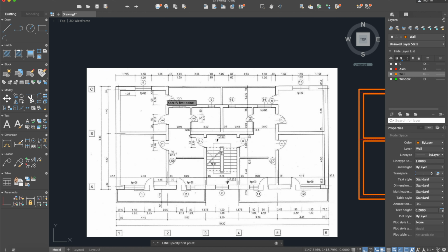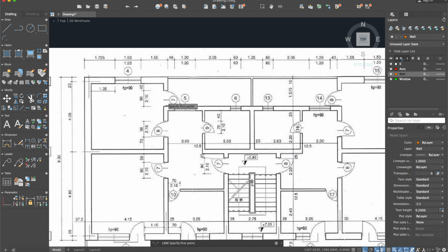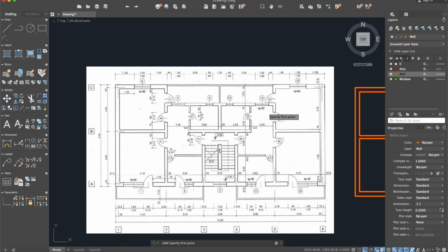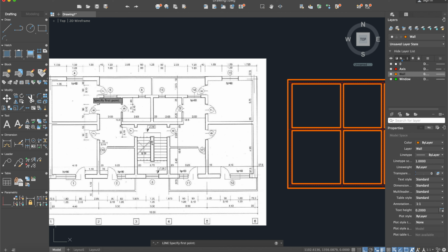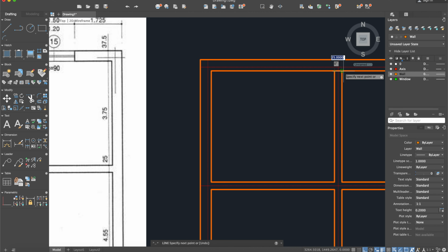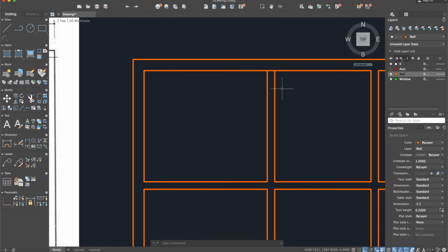But to build it, we need to do this door first. So this door is on a distance of 40, exactly on this. You can see it. So first thing I'll do, line, I'll put here 40. I can also disable this layer because I don't need it yet. Offset command again 40, and here it will be our door. I can delete it now.